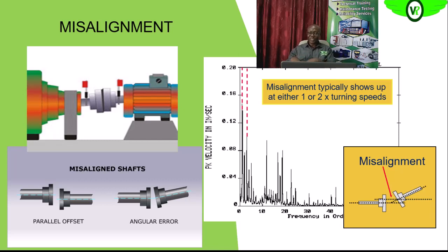We will be giving the electric motor more load than what we installed it for, because of that misalignment. And all of this increase in loading will affect the entire system. Remember, it will affect the heating of the motor. It will increase the load current, the heating of the motor, and the heating of all the electrical components, cabling and what have you, on the line to the point of input.